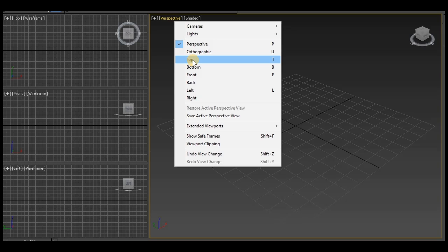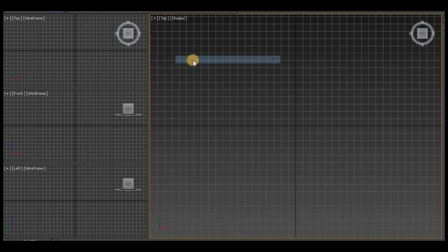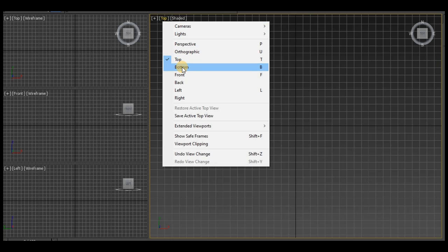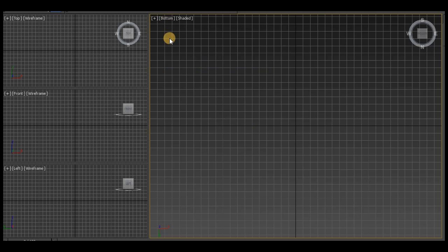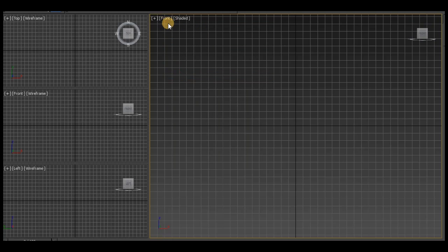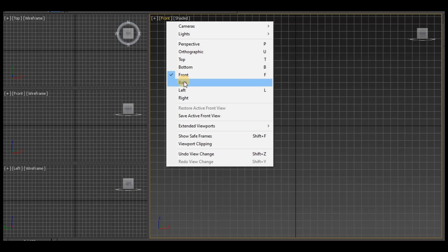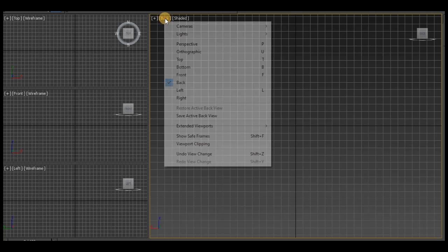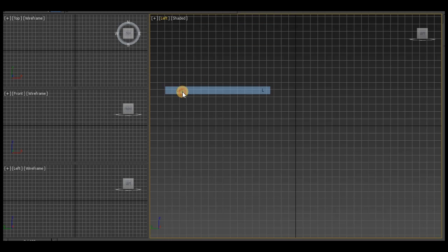To do so, click on the POV Viewport label. A layout will be displayed. Choose the viewport that you want to display. You can also use the Shading Viewport Label menu for defining the type of shading displayed in the viewport.